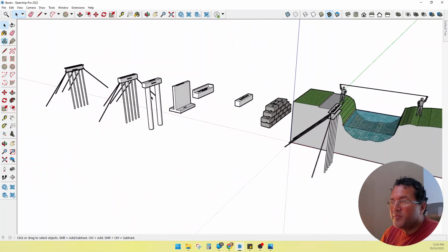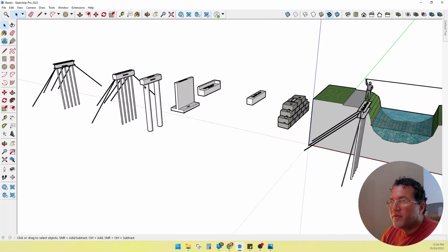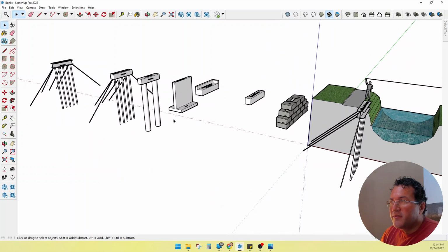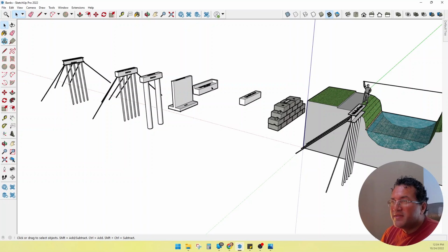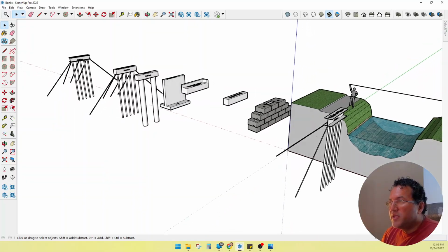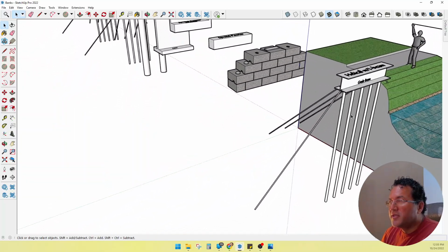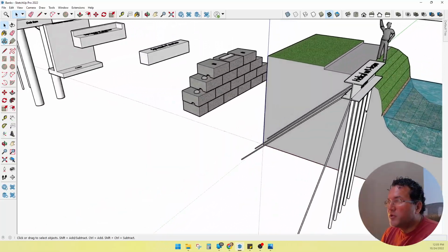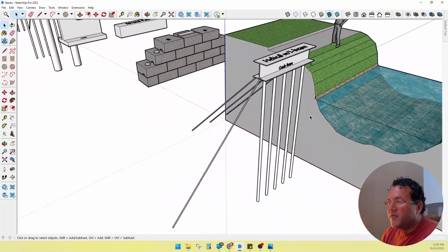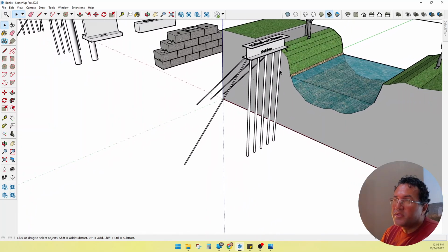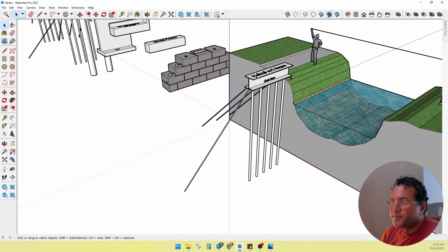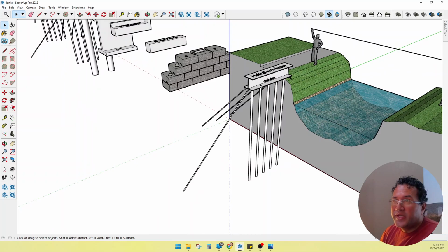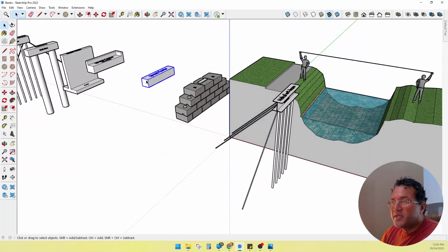Well, it's pretty comparable depending on the caisson options, all these with the longer legs. They're all going to be in the comparable ballpark. This is kind of medium expensive. These are really inexpensive. This is super inexpensive. But this, when you need it, you need it. When you need a solution that doesn't require any concrete, allows you to build really close to the waterway, and even if you have sandy soils, poor soils, mucky soils, we can drill through all that and get to firm, solid soils. So the helicals are a great solution for certain situations, but not all. Grade beams, these are by far the most popular.